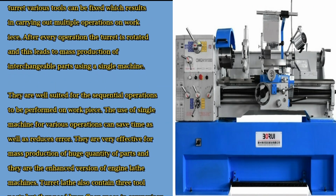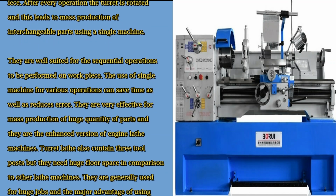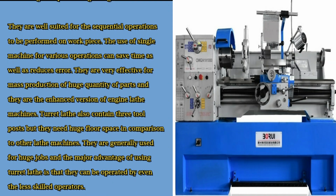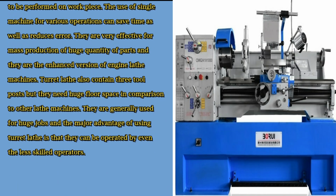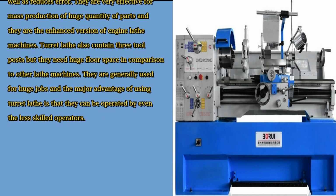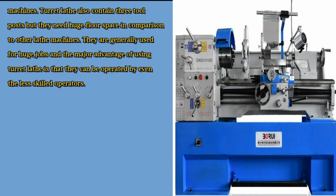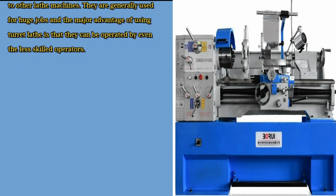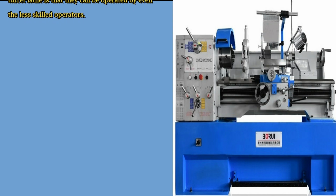They are well suited for the sequential operations to be performed on the work piece. The use of a single machine for various operations can save time as well as reduce error. They are very effective for mass production of huge quantities of parts and they are the enhanced version of engine lathe machines. Turret lathes also contain 3 tool posts but they need huge floor space in comparison to other lathe machines. They are generally used for huge jobs and the major advantage of using turret lathe is that they can be operated by even less skilled operators.